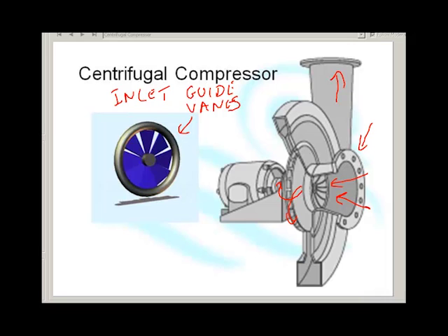Oh, now one thing I should mention, throughout all this I've been talking about unloading compressors by inlet guide vanes and slides. Nowadays, of course, there's another method we have of unloading a compressor, and that's by changing the speed of the AC motor. How do you go about changing the speed of an AC motor nowadays?